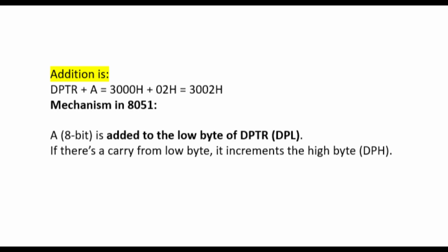Effective address equals DPTR plus A. But since A is only 8 bits, the processor adds A to the low byte of DPTR, which is DPL. So the addition becomes DPL equals 00H plus 02H equals 02H. Since there is no carry, the high byte DPH remains the same. So the final address becomes DPH, DPL equals 30H, 02H, which means the effective address is 3002H. Now the microcontroller goes to program memory location 3002H, reads the data stored there, and places that value inside